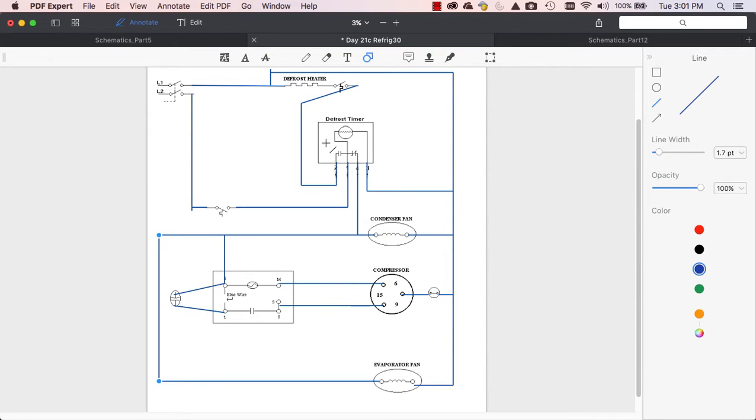So again, the compressor runs normally until the defrost clock says it's time for defrost. Everything down here shuts off. Everything up here goes into defrost. The system will continue to operate the defrost, and eventually, once the defrost clock is through its set point of number of minutes in defrost, it comes out of defrost and restarts my cooling circuit again. Notice there's no DTT on here. There's no way to avoid this going through the full defrost cycle.